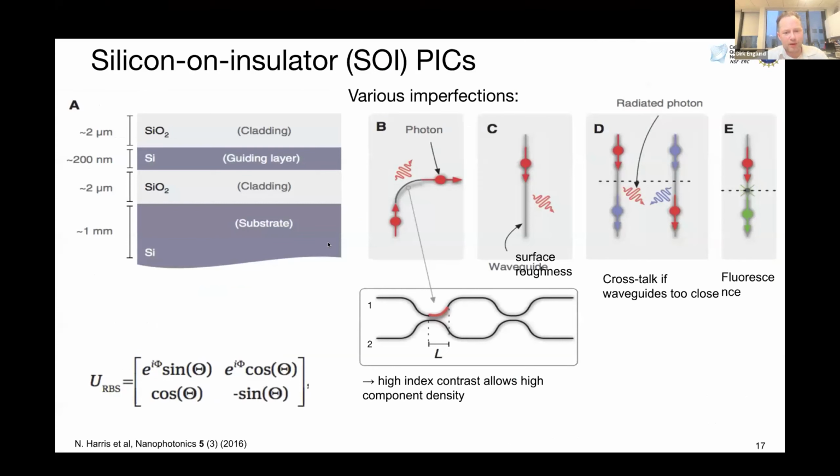So one really useful tool that's come about in the last few decades is optical waveguides, high confinement optical waveguides consisting, for example, of a silicon guiding layer surrounded by silicon dioxide low index cladding. Then by total internal reflection, an optical field can be confined in a wire defined by etching a silicon waveguide, as illustrated here.